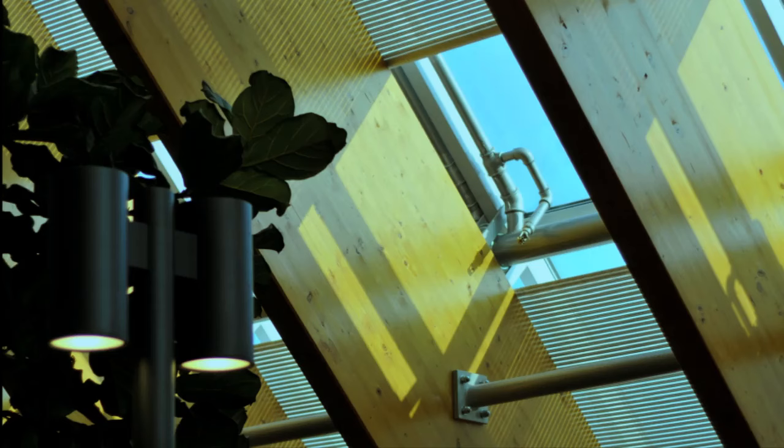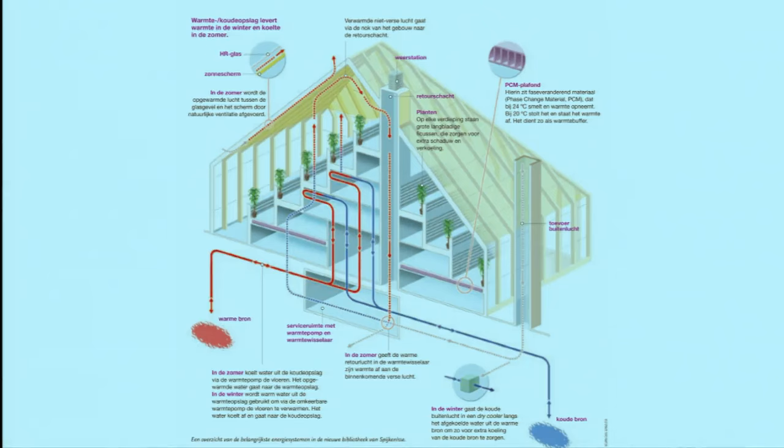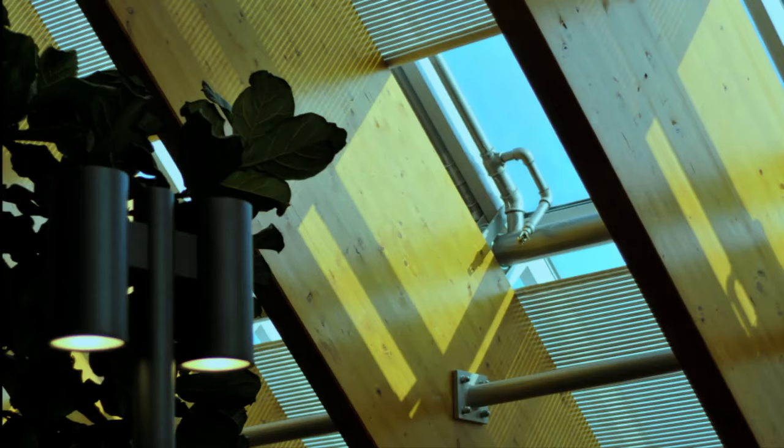So they can sustain the people less than the sunlight. And furthermore, the bad qualities of the glass, because it creates heat, it creates cold, we actually use by having all these pipes going through, which are also doubling as sprinkler systems. So in summer, they make sure that the water gets hot, and the hot water is stored, and in winter, the cold water is actually collected and stored. And so we use cold water in summer to cool down the building, and hot water in winter to heat up the building. So underneath the building are 2 really big tanks. We also have fig trees and all kinds of other small things to help with the climate, and it's fully computerized, so it actually works all by itself and costs next to nothing in maintenance.